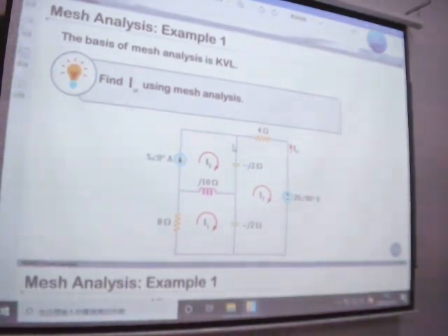Then we know we calculate out this matrix. Then we are going to see this vector. For loop 1, no source, so it's 0. Is it? There is no source here, right? For loop 2, the voltage rise is minus 20 angle 90 degrees. Is it? The problem is this one. How to write out this one?